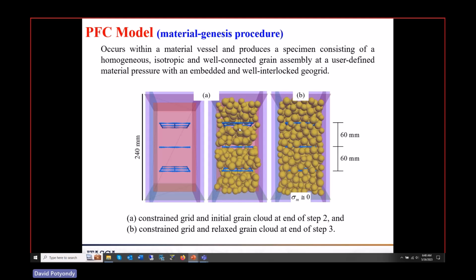So what I get then is, and when I generate them, I say keep going until you reach a certain number of balls, a certain porosity of balls. So you generate this cloud, but you basically delete all the guys that would have touched this. So now you've got this arbitrary, see the big overlaps of this system? Then what you do is you make all the surfaces of these particles have zero friction coefficient. And then you just cycle the model.